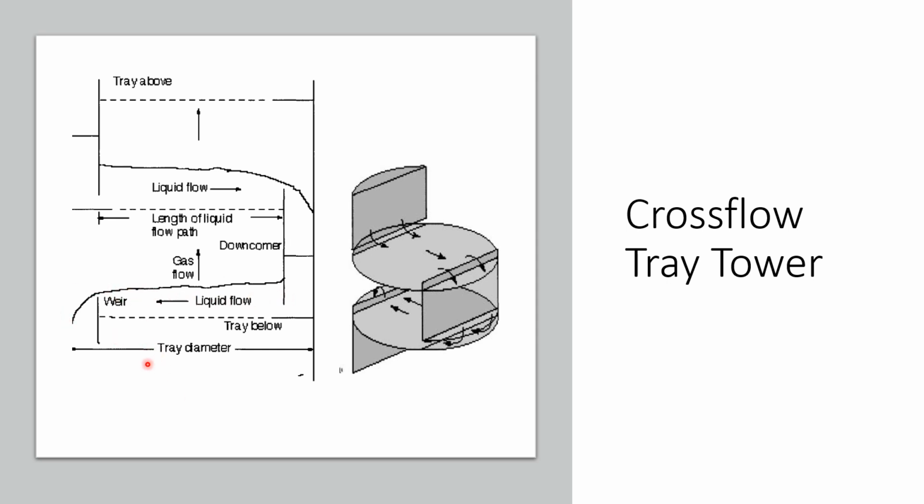The gas is passing from the bottom to the top through the holes and then through the liquid, where they would have the intimate contact with the liquid phase, and hopefully mass transfer will take place before the separation of the gas and the liquid. Now remember, we are always trying to avoid flooding. At the same time, we need to make sure we don't have any weeping.